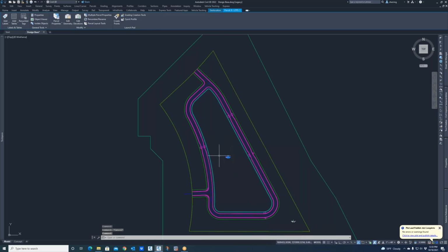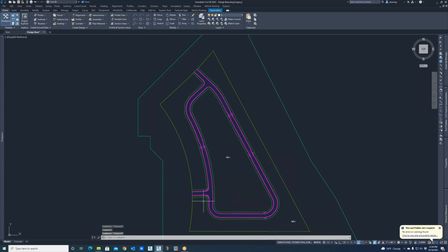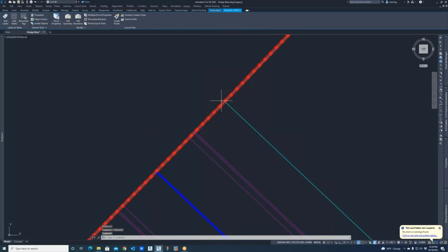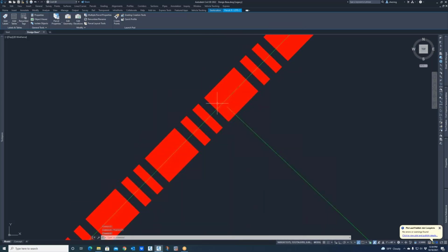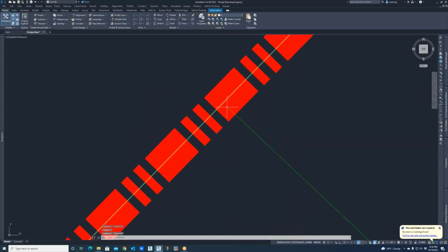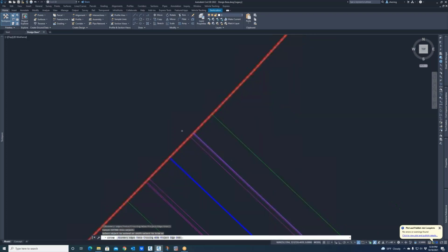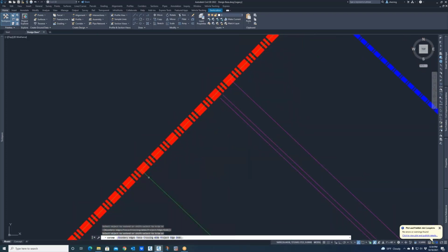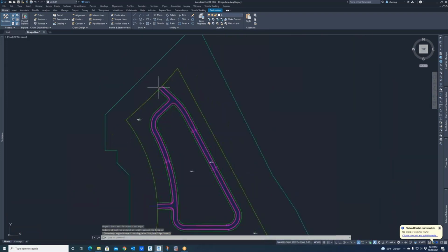So now that parcel 1 is just that area in the middle, what it's looking for is kind of a closed object. So up here at the top, you can see those lines didn't quite extend to the boundary. So you can use the extend command. So I'm just going to type in EX. I'm just going to extend that line and this line. Hit enter.